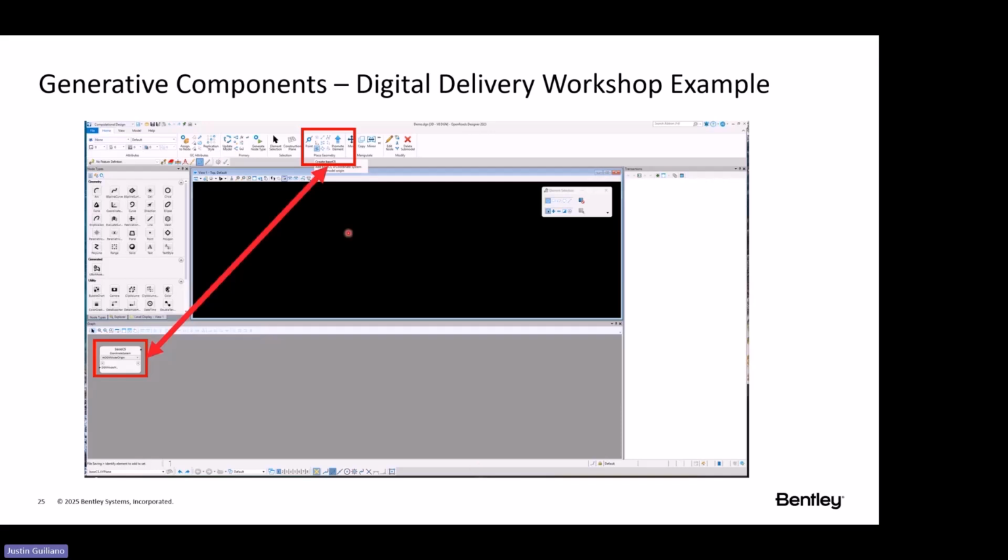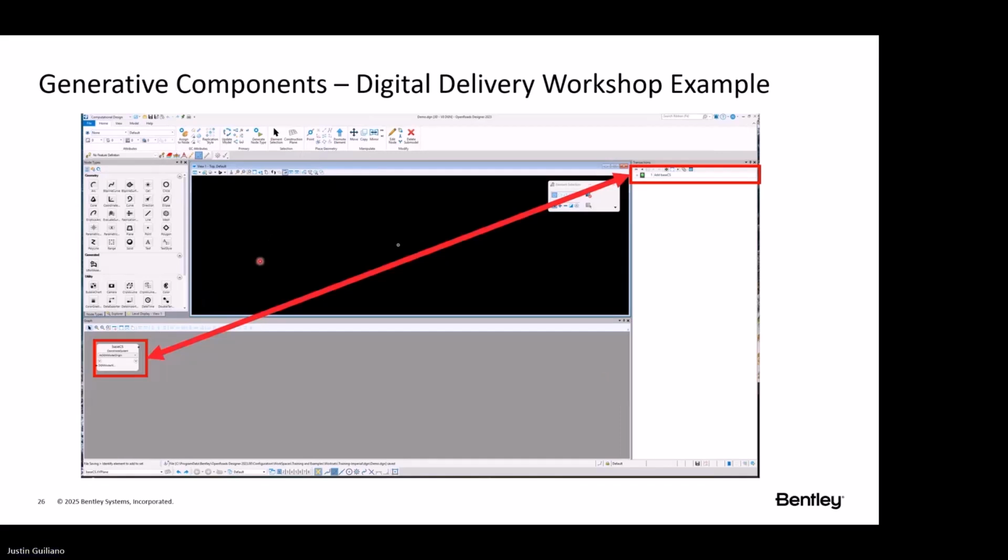But here we see basically what we're doing is we're just clicking on our base coordinate system up here. And once we clicked on that button on the ribbon, it gave us this node called base CS. And that's what it does. It places the node here. Now, once we hit save, we're going to see that transaction get listed here. And again, what this is doing is recording all of these steps or nodes that we have done on our graph and saving it as a record here. And as we progress and start building more and more nodes, we can save and we'll see transactions populate here in our transaction list.